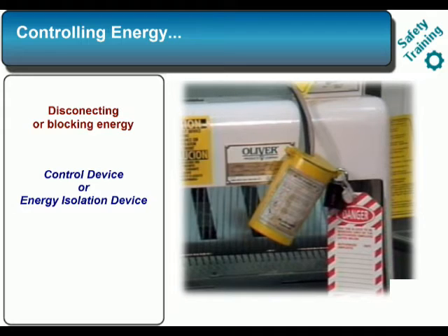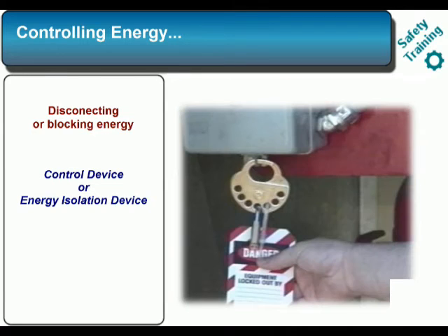Covers are used to lock valves. Electrical breakers use breaker clips, and piping systems use blanks to block flow. Cord and plug equipment should be locked out before repairs or adjustment. By placing a locked plug bucket on the plug end of the electric cord, you prevent anyone from restarting the equipment. Whatever type locking device you use, make sure that no one can remove the device without unlocking the lock.